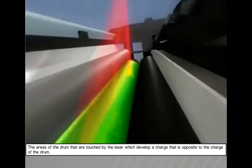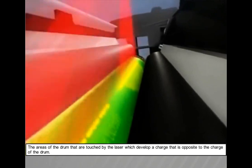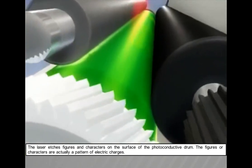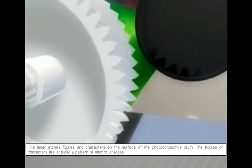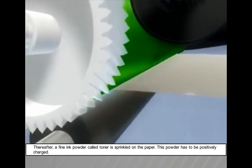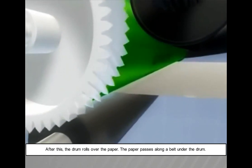The areas of the drum that are touched by the laser develop charge that is opposite to the charge of the drum. The laser etches figures and characters on the surface of the photoconductive drum. The figures or characters are actually a pattern of electric charges. Thereafter, a fine ink powder called toner is sprinkled on the drum. This powder has to be positively charged.